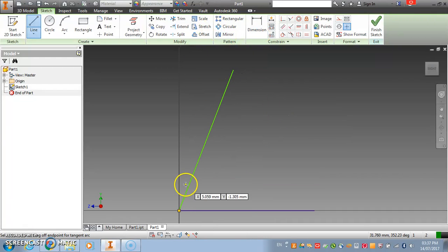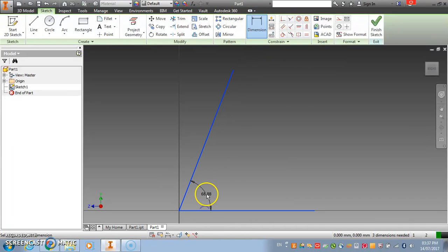Next, let's say for example the bend angle that I have for my project is 70 degrees. So I'll just key in 70 degrees for both lines. This is just lines. We need a closed surface to make sure that we can extrude.